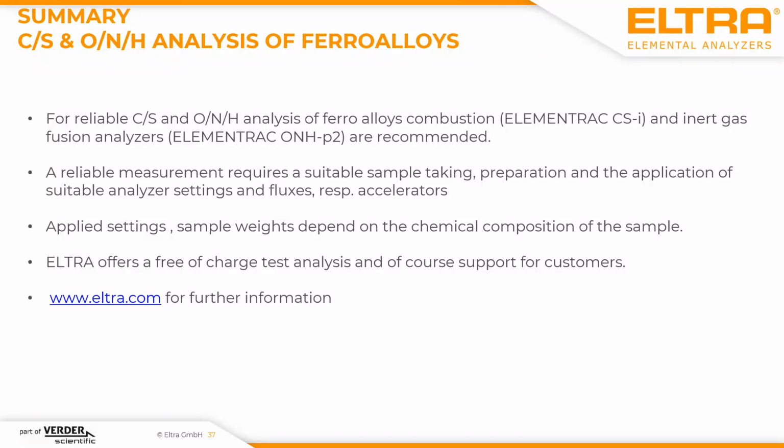A ferroalloy with 10% of titanium is something very different in comparison to a ferroalloy with 90% of titanium. This could mean that you need different settings, different flux material and a completely different application. For a correct analysis of ferroalloys, always consider not only the analysis steps, but also the sample taking and the sample preparation process.